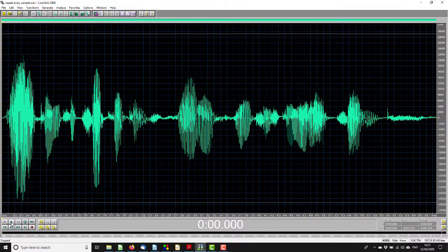Note that in both cases the pitch and the speed are linked. Increase the pitch and the sample plays faster, decrease the pitch and the sample plays slower. This is not a problem in our case actually, because we're using single waveform samples that we can repeat as often as we need. Okay, so we've played our sample at twice and half the original frequency, but what if we want to be able to play it back at any frequency?